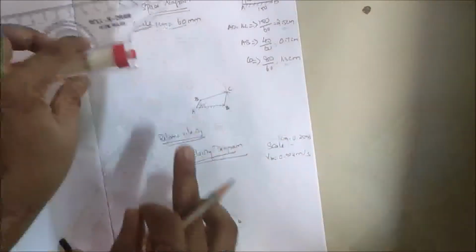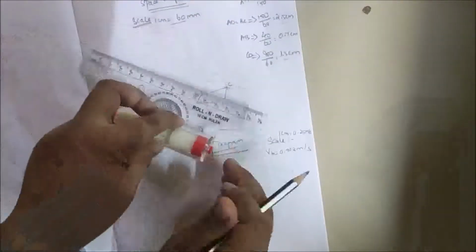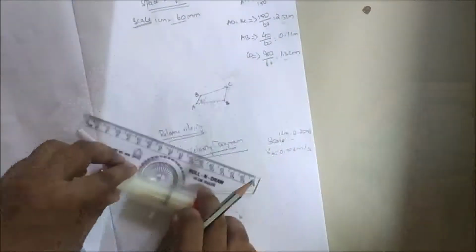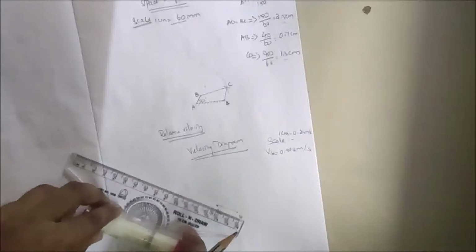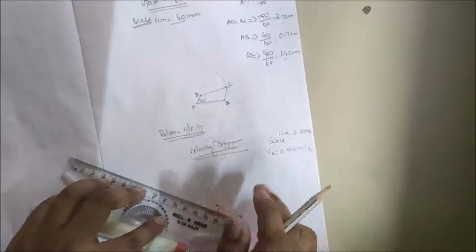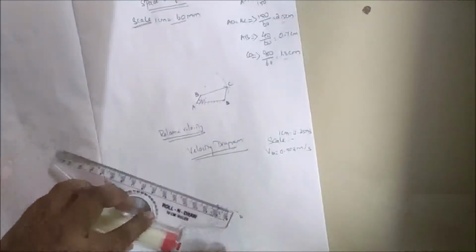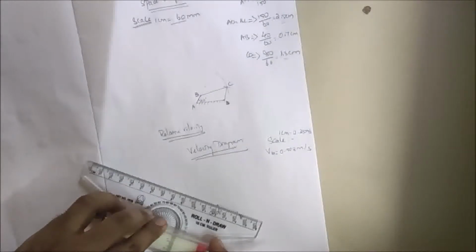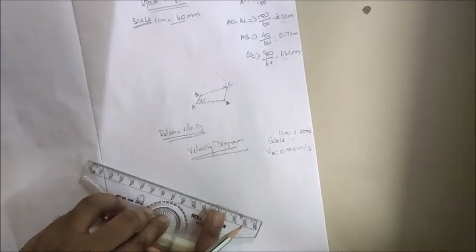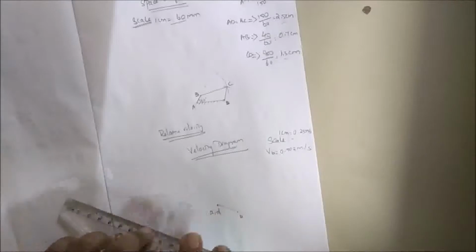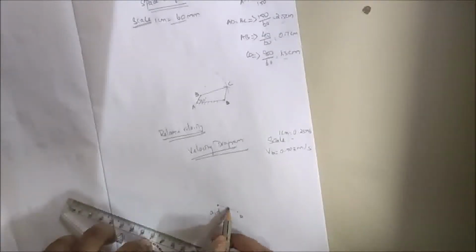Now, if this 90 degrees touches here straight to the link, this is going to be the perpendicular. Slide it like this and place it at this point; from there, as per our scale, take 2 cm. So we have drawn this as 2 cm. Looking at the dimension, 2 cm from 12 to 14 comes out correctly. So this represents B. Now the notation should be noted as VB, like this.